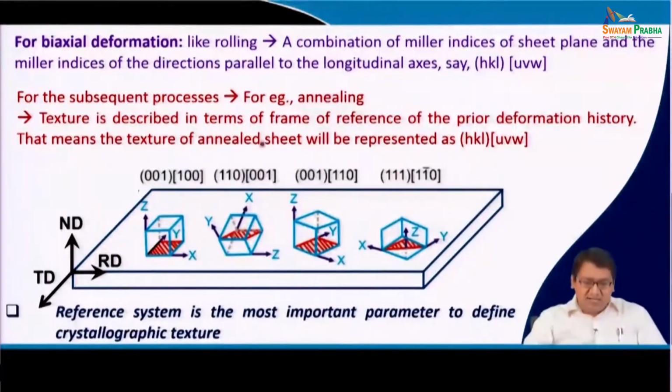On the other hand, one can observe a few grains with this kind of texture, the unit cell is shown here. This is the 001, 110 type of texture, and such grains will also be present in a higher volume fraction, but they also have to be separated, that is, spatially apart.